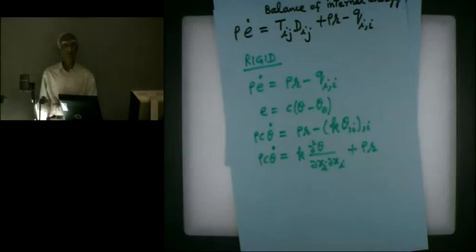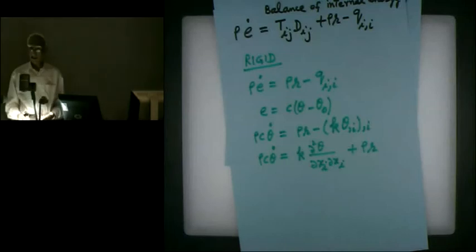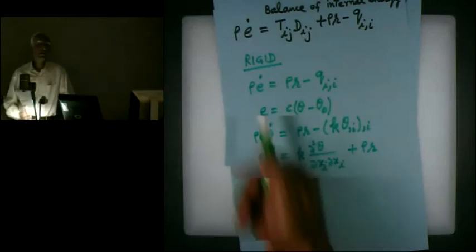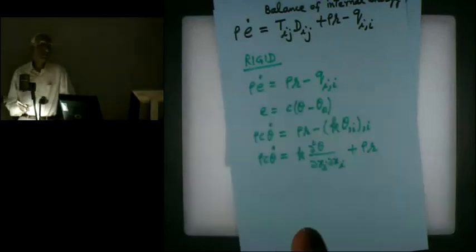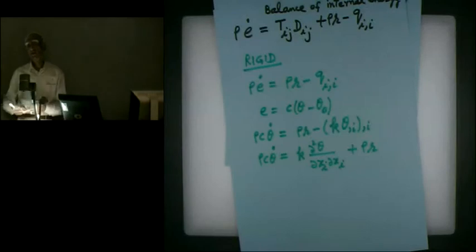This is the equation you use to study heat conduction. Diffusion equation? Yes, you can say it's a diffusion equation, because this is a diffusive term. So this is heat conduction in a solid, and if you have a fluid, then theta dot will be different, but since I took the body to be rigid, I should not really say a fluid. A solid is more like a rigid body than a fluid is. Or you are neglecting the deformations of the body.